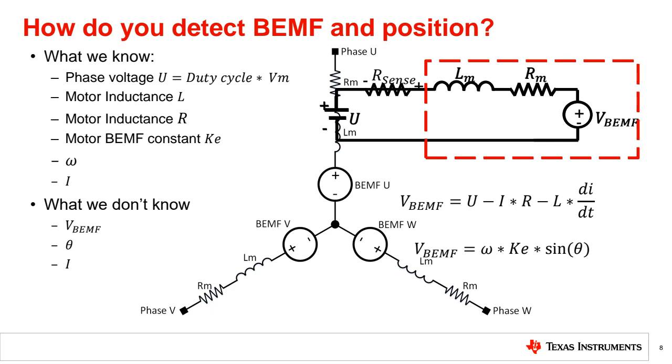Oh, it's possible. Another method: there are many ways to sense the current. One cheap way, don't forget it, is to use shunt resistors. Using the shunt resistor and an ADC, the current of the phase can be read.